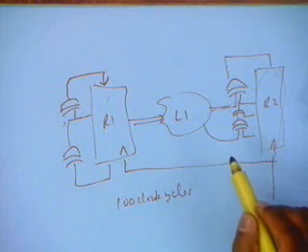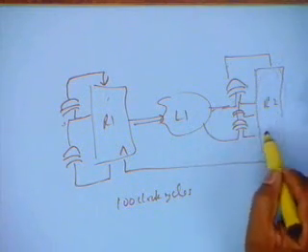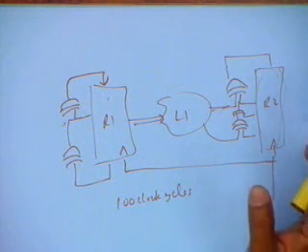So that is how the design of this is concerned. There is some analysis required to design it, but once you design it, you will end up with a different number, and this becomes the signature of the circuit. This signature can be tested against the stored signature to say whether this logic is correct or incorrect, so faulty or not faulty.